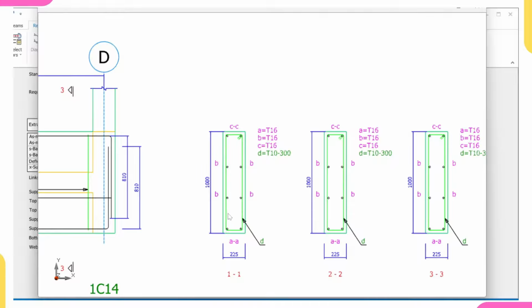You know, this is a very deep beam. If I do not include this web bar, this beam might twist and fail due to twisting. So to prevent that twisting, we include this web bar. You must include web bar even though the software does not provide it for you. Once your beam depth is more than 600, you must have web bar to prevent that twisting from occurring.